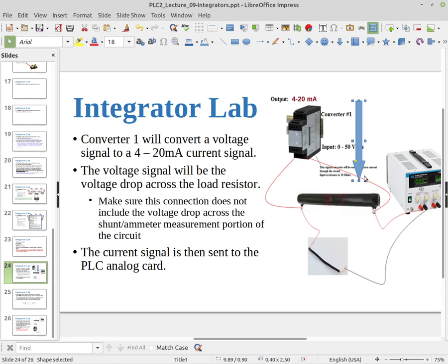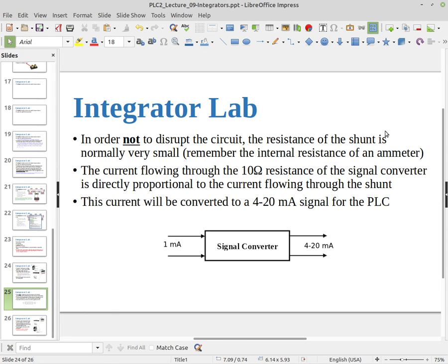that would be 5 amperes. And what you're going to find out when you actually start doing this is the power supply can't supply 5 amperes, so it's going to go into constant current mode, and we can get about 2.5 to 3 amperes out of this power supply. So in reality, the maximum current that we're going to get is maybe about 3 amps. But we're going to plan on a maximum of 25 volts across the 5 ohm resistor.